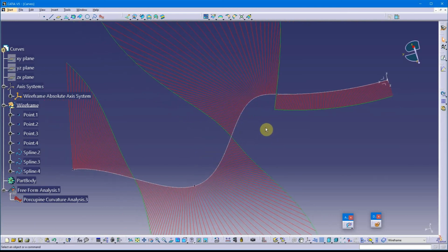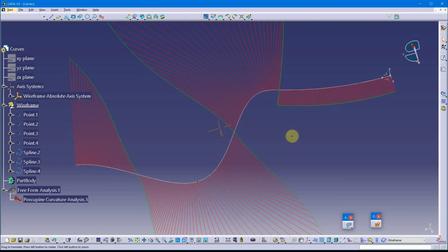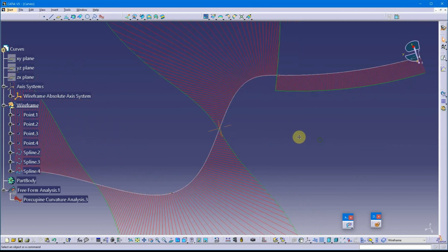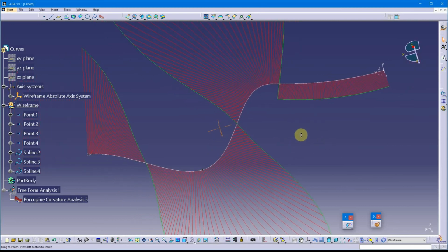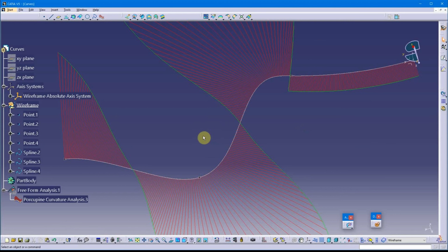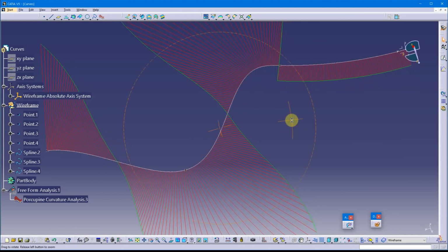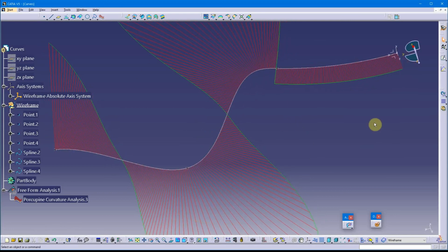So that concludes it. Again, remember how to do this in CATIA. Remember how to do it with a spline tool, and remember the four types of continuity: G0, G1, G2, and G3, and the last one, G3, is acceleration continuity. And also remember the degrees of curve: first, second, third degree, fourth degree. What's the smallest degree you can have and have a point of inflection? That would be a third degree. So please keep all that in mind. Thanks, and have a great day.